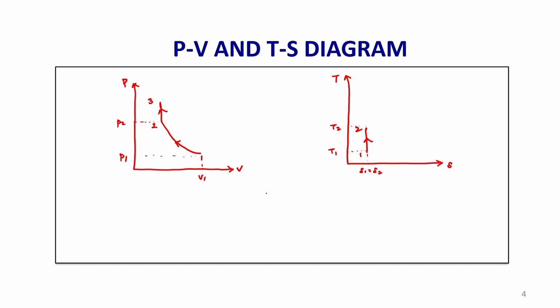Here heat addition takes place in 2 stages. Heat is first added at constant volume, then heat is added at constant pressure. So, this is the speciality of this cycle. That is why it is a combination of Otto cycle and diesel cycle in terms of heat addition, because in Otto cycle the heat is added at constant volume, in diesel cycle the heat is added at constant pressure.